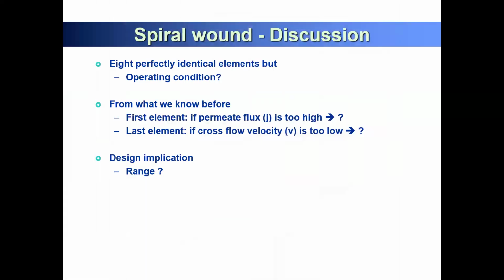Professor? Yeah. So in a pressure vessel, there are 7 elements. Yeah. And every element is subjected to different osmotic pressure, different concentration. Yes. So the rate of fouling and scaling will be different for every element. Yes. That's exactly, depending on the pre-treatment. So we need to design the pre-treatment carefully.